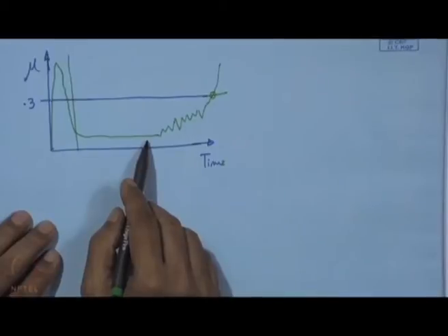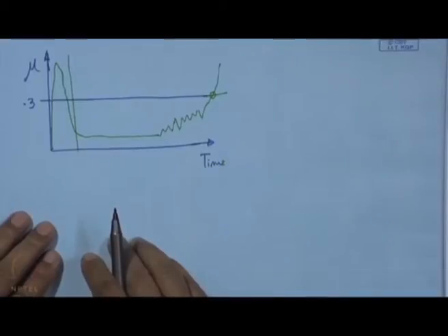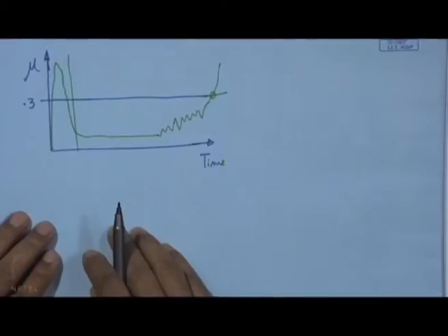Now, to get a very good value, obviously, as we said at the very beginning, the roughness of the substrate surface, its high points or surface asperities, apart from the chemical inertness or very low chemisorption, those conditions are there. The hardness of the substrate should also be properly monitored and taken care of, and only then can a tribological coating on top of that work.